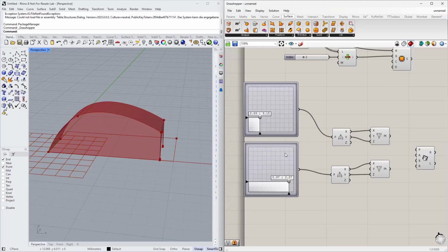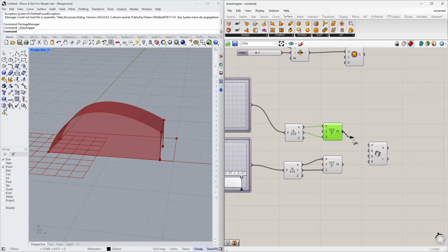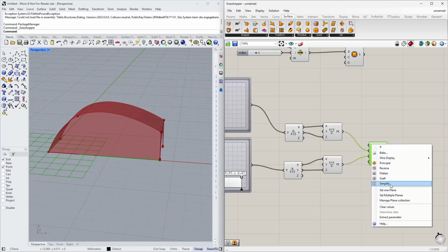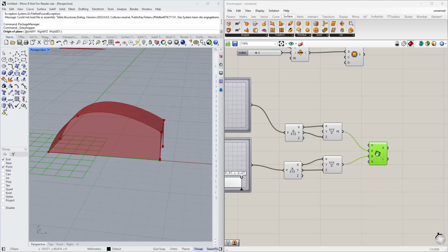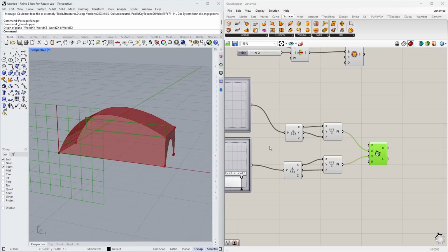This time, yeah, no, actually that's already okay. I can connect them as definition nodes for my rectangle. The rectangle can be placed in any plane, as you can imagine. So I can define the plane by setting it here graphically, or in the Rhino log, or however you call this area here on top. And I would like to have the rectangle in this ZX plane. Okay, yeah, that's now in the right plane.